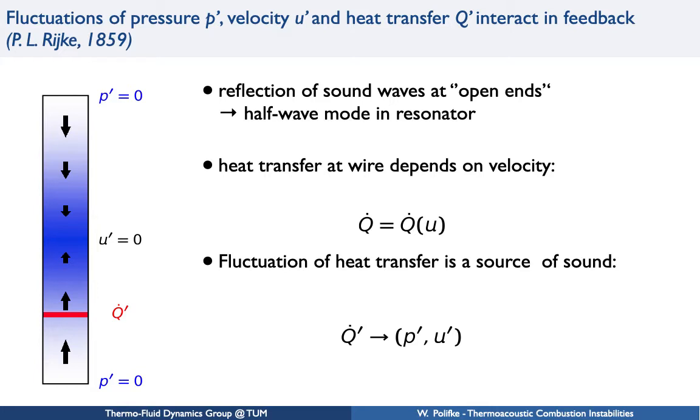And this increase and decrease of volume is what is a monopole source of sound. Now, in a stream of gas, heat transfer or heat addition in general is also a source of volume. Why? Well, because the cold stuff has lower specific volume than the hot stuff on the downstream side of the heat source.